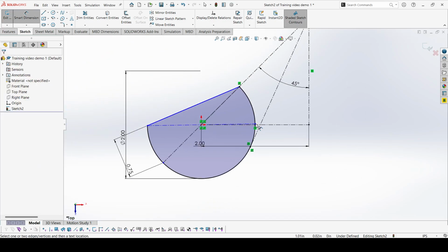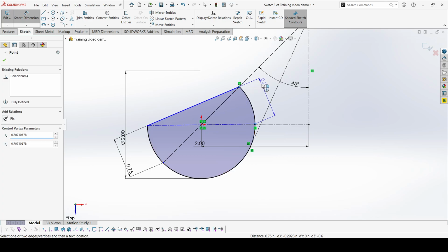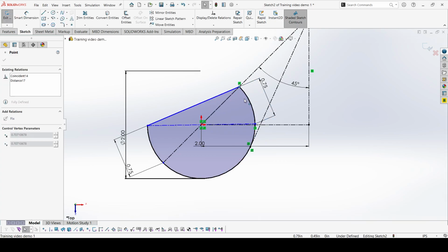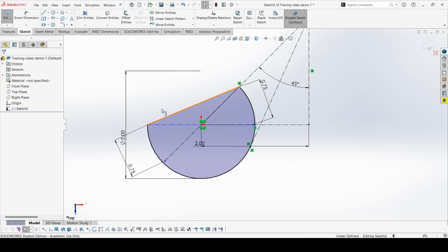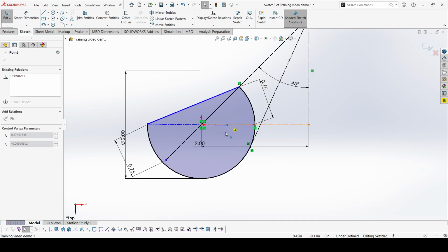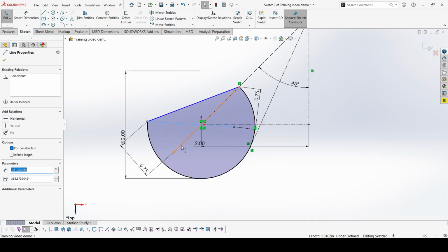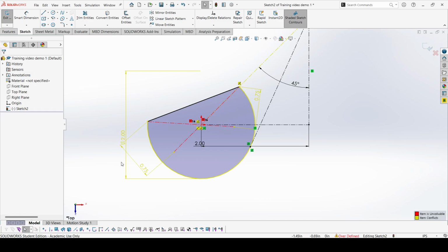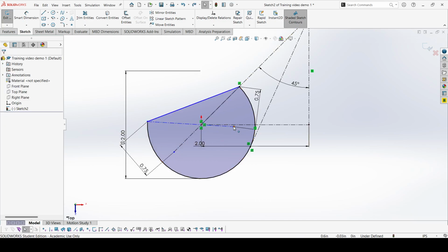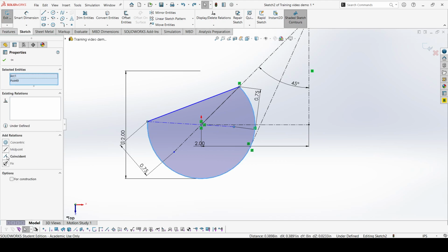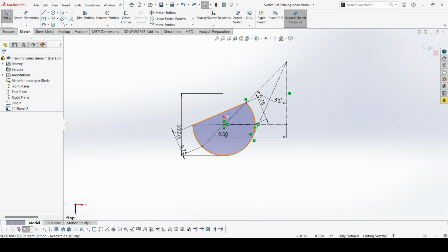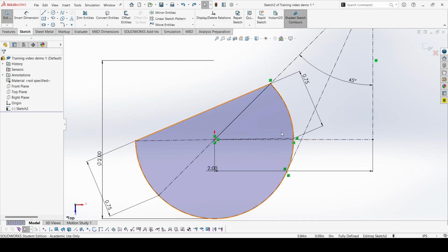However, if I set the distance between these 2 points to 0.75, it's nice, and, where did our hand... Let's see. Now, this is still saying it's undefined. Sometimes it'll say it's undefined and you have no idea why. And there's why. These were never defined as equal, which is very interesting that SolidWorks doesn't do that. That's conflicting geometry. Interesting. So, instead, you know what I'm going to do? I'm going to make that coincident to the circle. Now, it's fully defined.